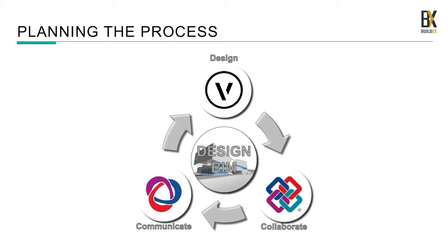As part of the design phases, clash detection is one of the processes that you will perform. This process uses other specialized tools or software such as Solibri Model Checker or Navisworks. It is important to mention that we support the BIM Collaboration Format directly in Vectorworks.